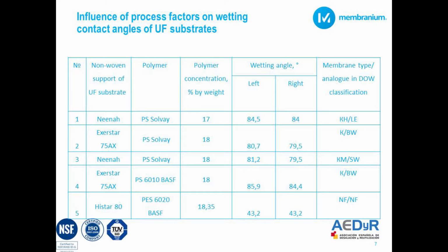What is the most surprising: you have the same polymer, the same non-woven support for the ultrafiltration substrate, the same concentration, but a different producer of the same polymer, I mean polysulfone, namely Solvay and BASF. Let's compare 0.2 and 0.4. You also have a different contact angle.